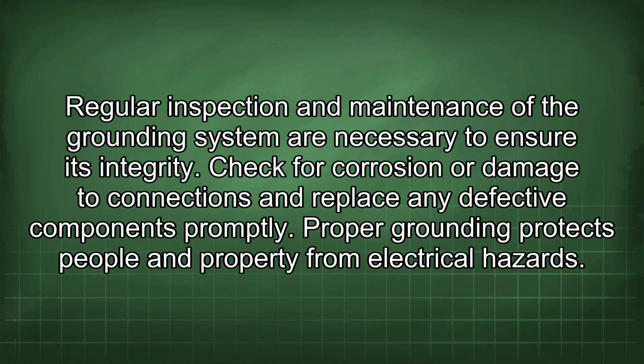Regular inspection and maintenance of the grounding system are necessary to ensure its integrity. Check for corrosion or damage to connections and replace any defective components promptly. Proper grounding protects people and property from electrical hazards.